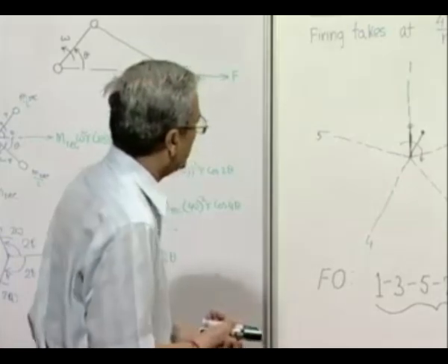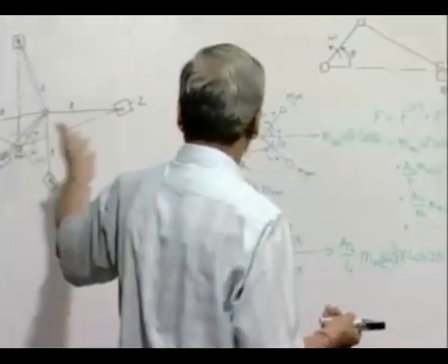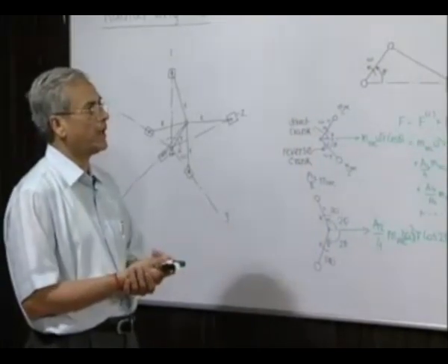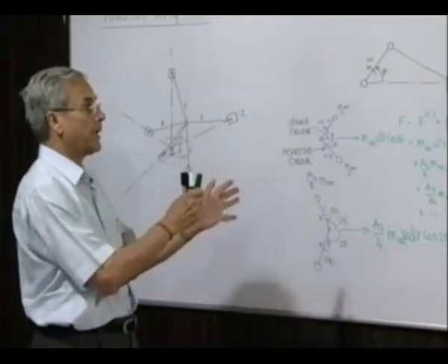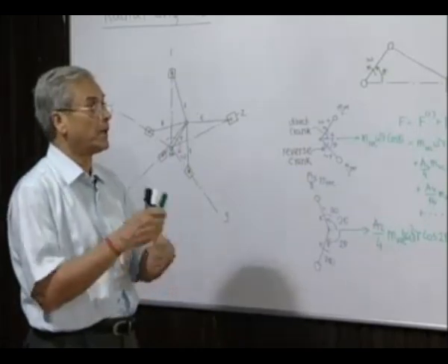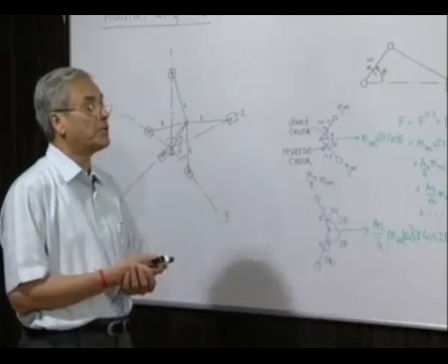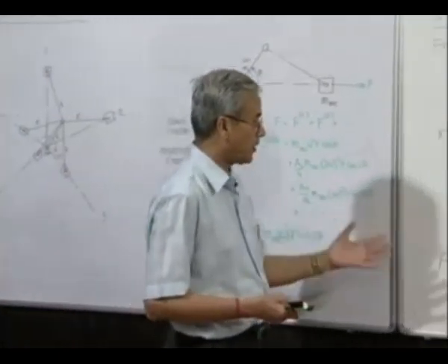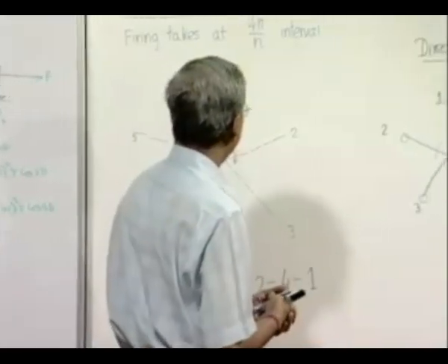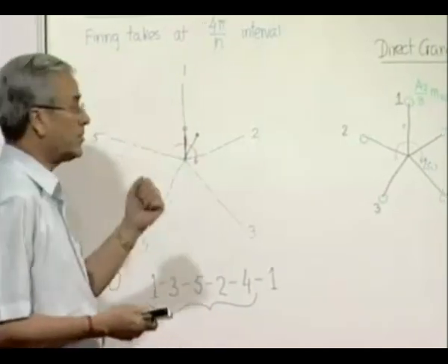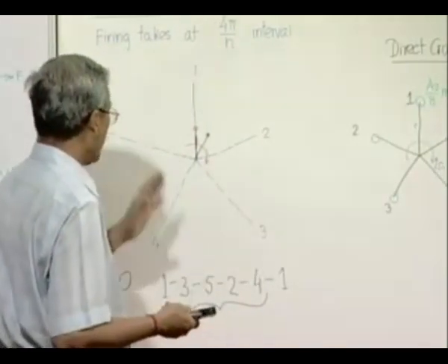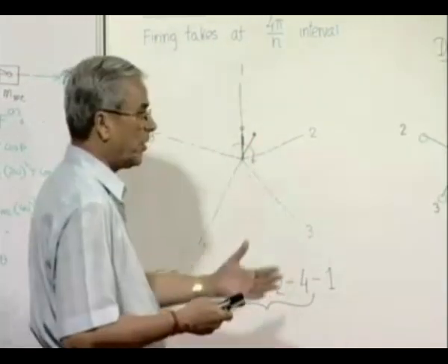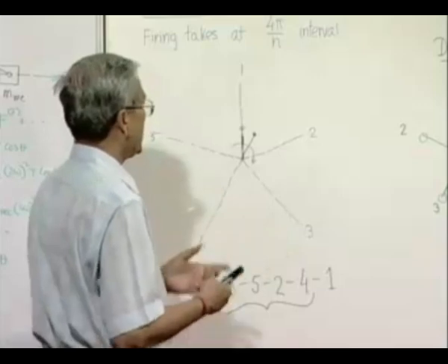And radial engines, IC engines, these we have seen what is the situation. We have also seen how we can actively attach some mechanism to an engine to produce unbalanced forces which can balance or neutralize the unbalanced forces of the original engine. We have also seen the importance of firing order, and lastly we have also seen that in case of radial engines with 4-stroke cycle operation, we must always have odd number of cylinders if we want the firing to be uniformly placed and all the cylinders are to be fired.